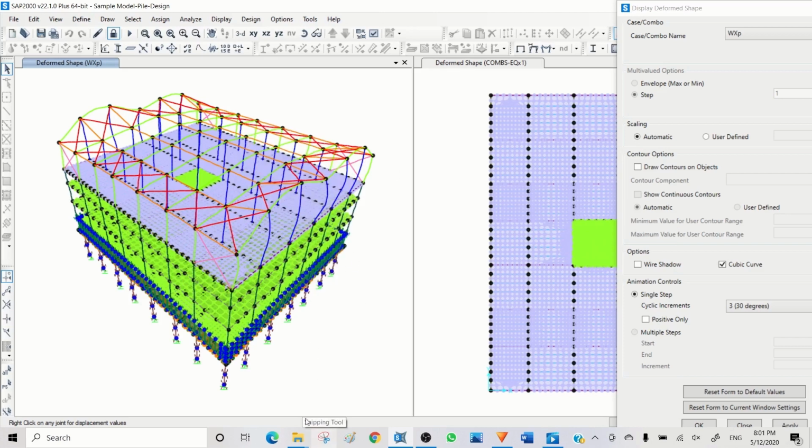You need to increase the stiffness, regardless of the strength requirement. So these are the basic things we need to do. We need to check the global stability of the structure. We need to check the displacement. If everything is okay, then we can go for the detailed design and see from a strength point of view if the elements are okay or not.